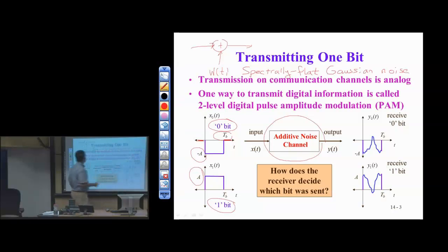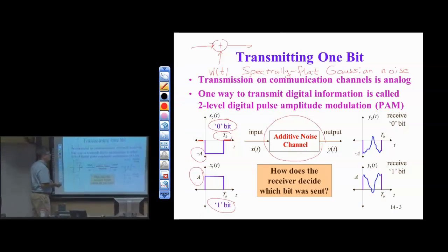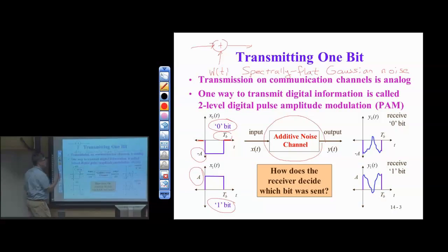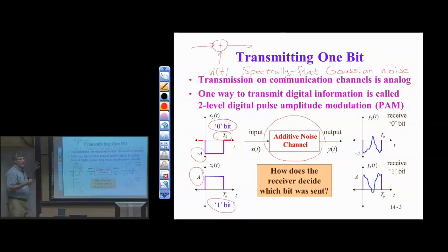So each amplitude value for any point in time little t, W of t takes on a value that's random. That random value follows a Gaussian distribution. That Gaussian distribution, for our purposes, will have zero mean and variance sigma squared. And sigma squared also represents the noise power. We'll talk about this in the next part of this lecture 14, so in part 2.